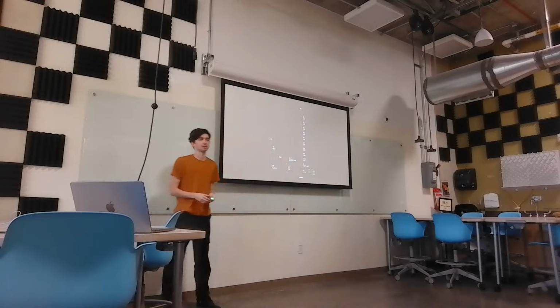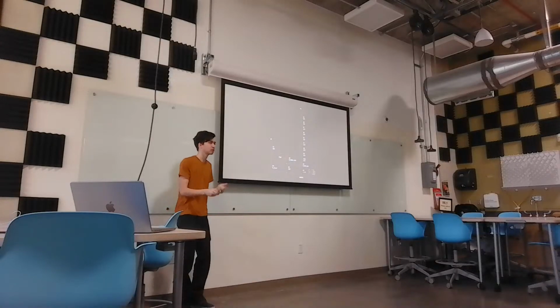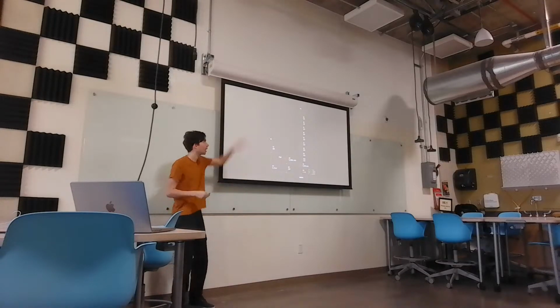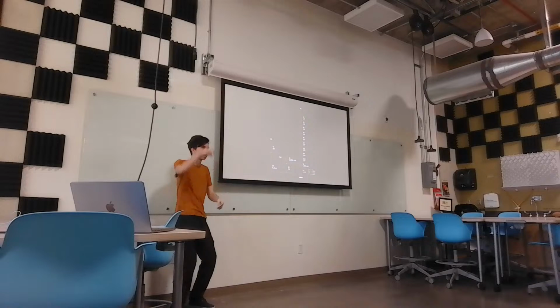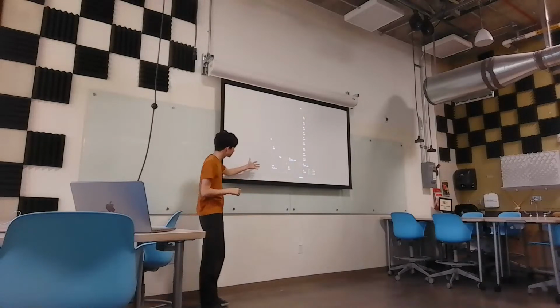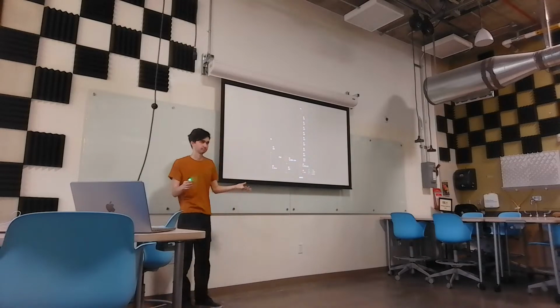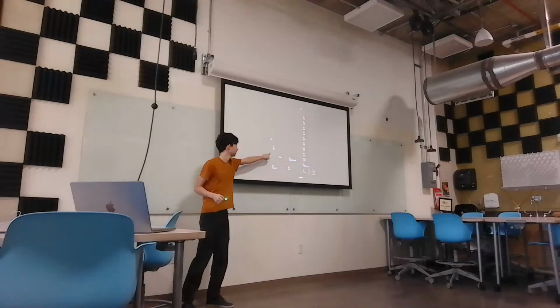Okay, fine, we can put a current in the transistor that makes the current go out. How do we make sure that it is regulating the current, so that no matter what the input voltage is, there's a constant current going through it? What I did, and this might look a little weird to you, is I have this Zener diode. It has a reverse breakdown voltage of 1. So that means the voltage here, no matter what is here, is going to be 1 volt.